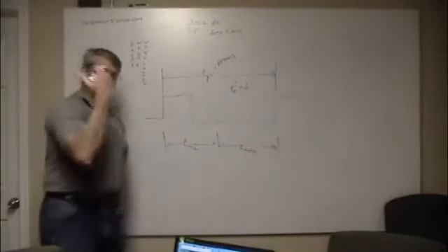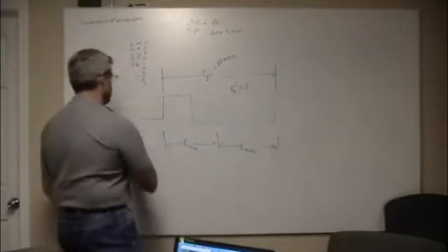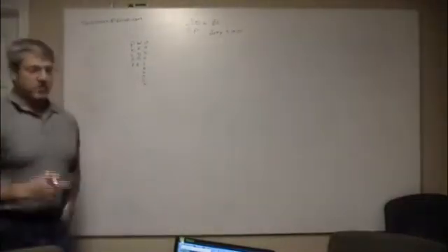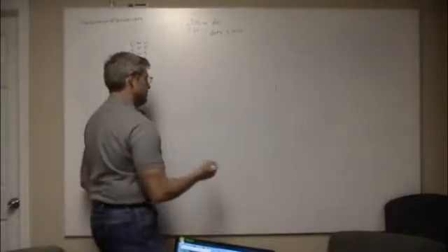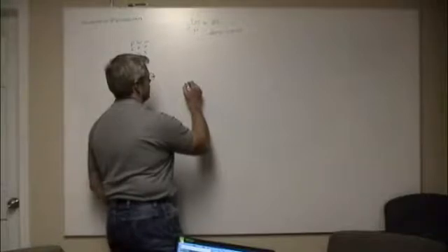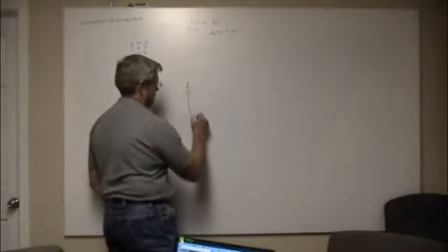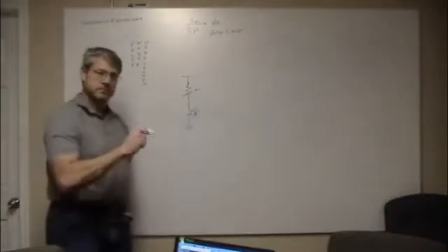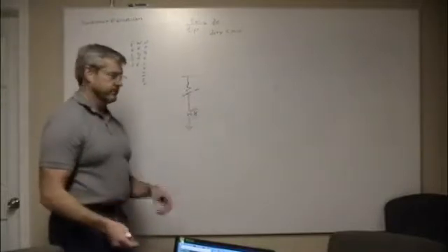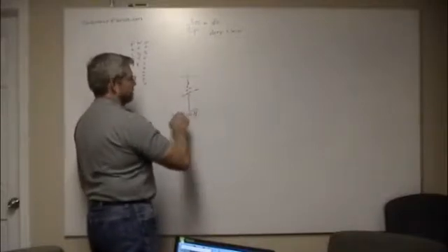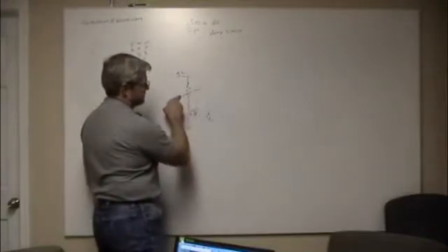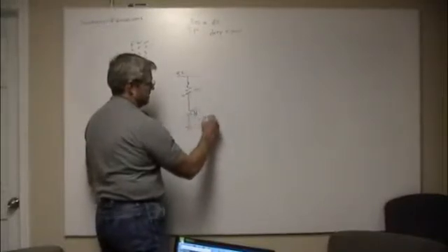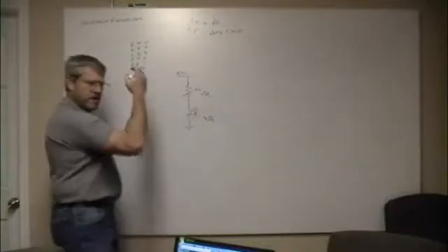So we talked about why you would want to do this. If you go back to the original electronic stuff we talked about, let's talk about a light bulb. How do you dim a light bulb? There are a lot of ways, but I can use an adjustable resistor, twist the knob. As the resistance goes up, the current goes down, the light gets dimmer, vice versa. The problem with doing this is, let's say this is 5 volts and this is a 1 watt bulb. When this is all the way off, this draws 1 watt. When he's half on, he's doing about a half watt. So you're always using all the power all the time.